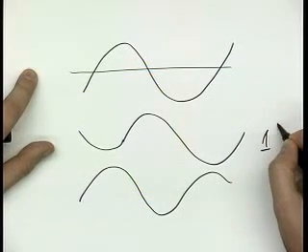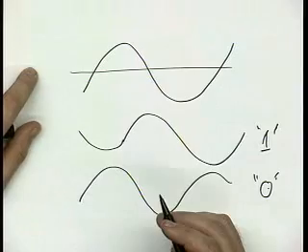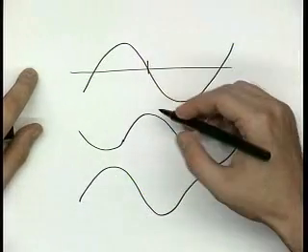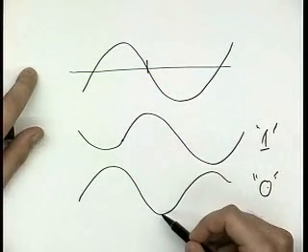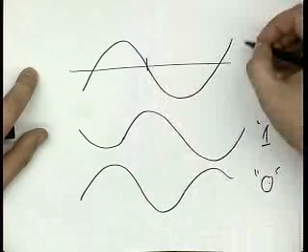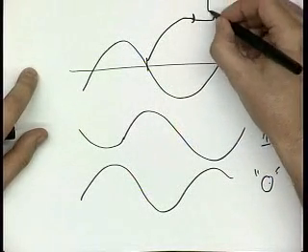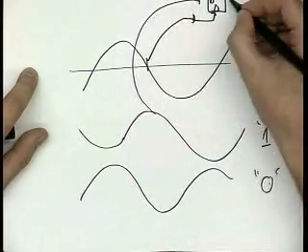So that's 1, 0. So I can demodulate this in a very straightforward way by just looking, whenever I go through 0 on the I, at what state Q is in. If it's high, that's a 1. If it's low, it's a 0. And so I could basically take that, put it in as the clock of a D flip-flop, and take this and make it the D part. What I do